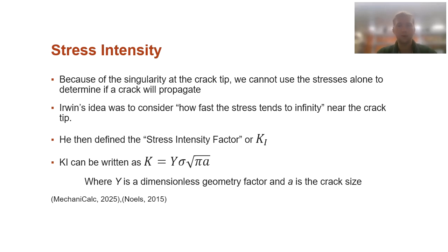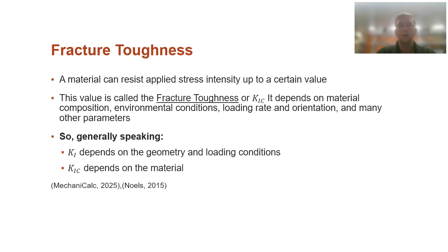So why does the stress intensity factor even matter? Well, because we can bring in fracture toughness. So at what point will a material break? And this is important. This is a pop quiz later, so keep this in mind. Essentially, material can resist this stress up until a certain point, and that's when it'll break, according to LEFM.